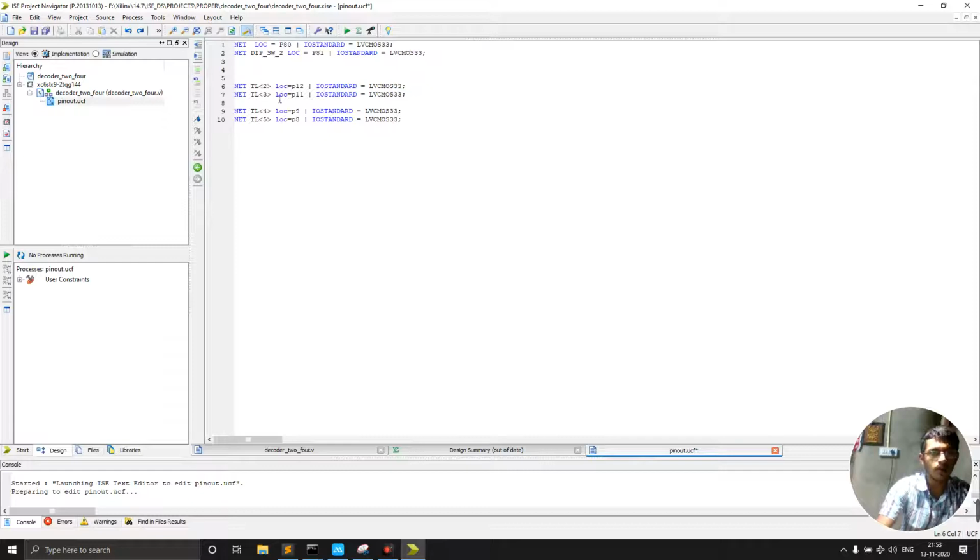Okay, so here, instead of this, I have to write Y, then here also Y, and here also Y. Okay, then I have Y of 0, Y of 1, Y of 2 and Y of 3. Since we use this as a vector, you have to write it like this: Y of the smaller and greater symbol, in that 0 1 2 3. We have the 0 to 3 as the output, and the input is the DIP switch.